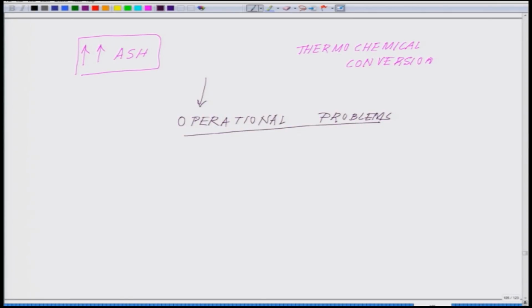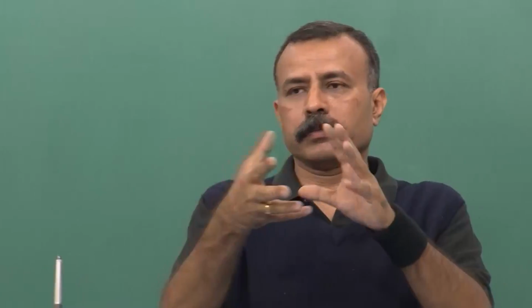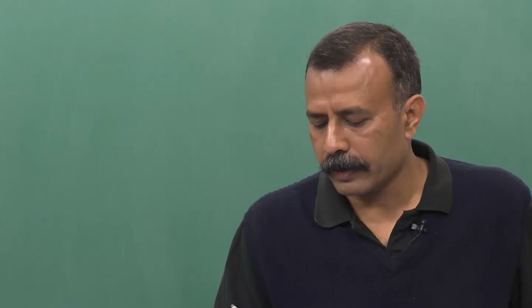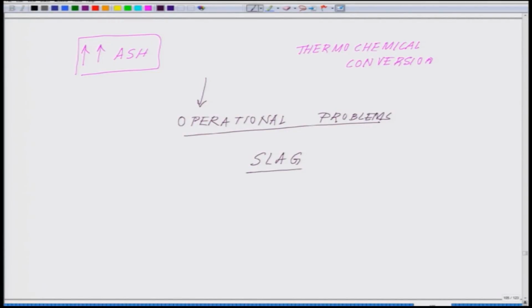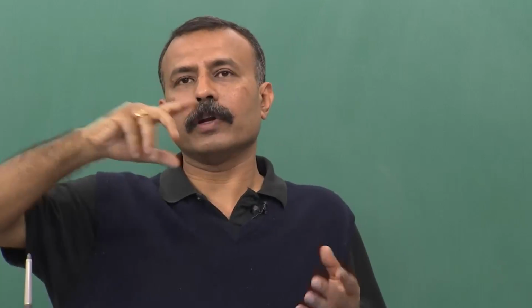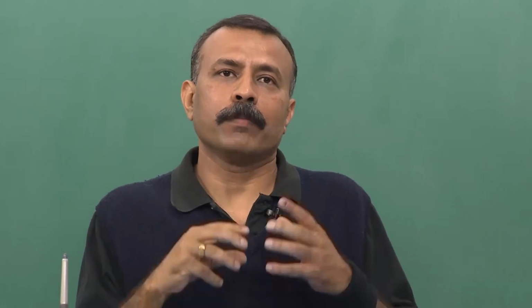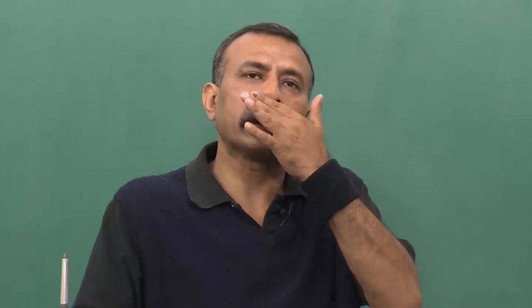During the combustion, ash can react to form something like a slag or a liquid phase, and they block the processes. So, what happens when there is a thermochemical process, some of this ash combines together with other reactants and forms something called a slag. Okay. And this slag, what is formed, in a reactor, they kind of deposit, and those depositions are not at all helpful. They block all this.